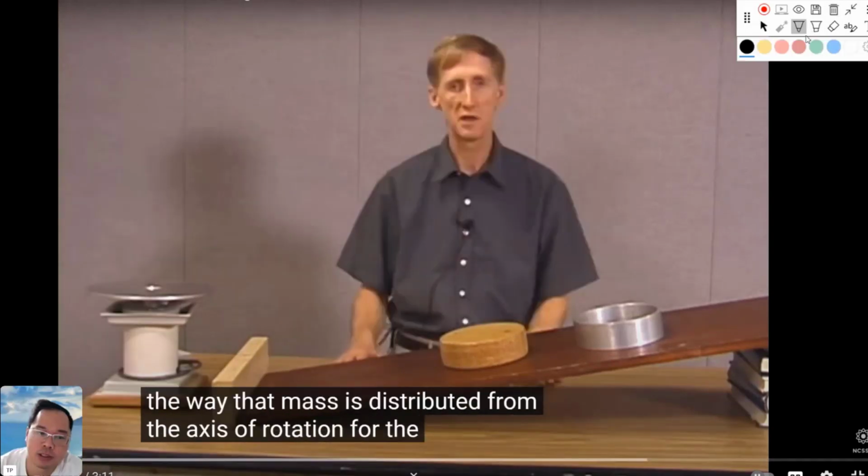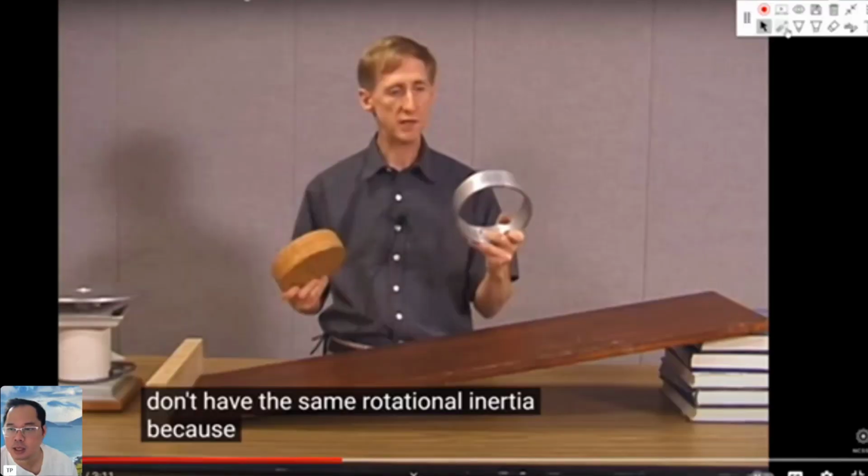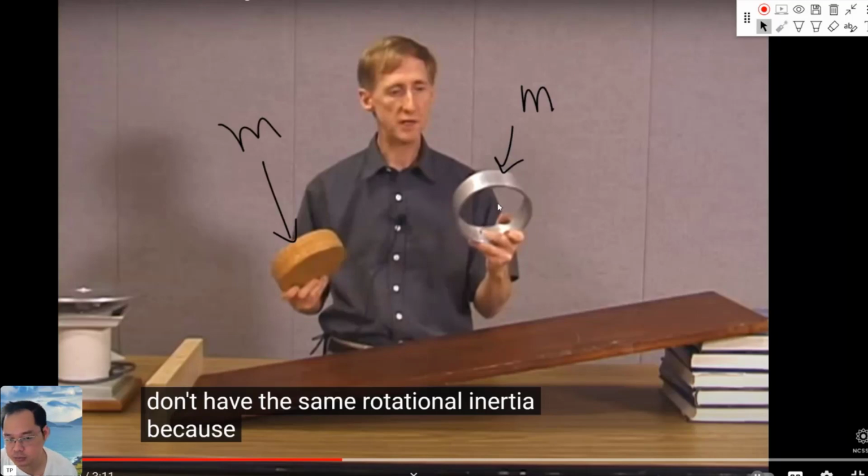With I, he just said that it depends on two things. It depends on the masses of the components of the object and the distribution of the mass. Distribution means how the mass is located on the object. For example, this is the solid cylinder. It is different from the hollow one, where the mass is distributed only on the outer ring. They intentionally made the two objects have the same mass, m and m, but a different distribution of the mass: hollow, empty, and solid.